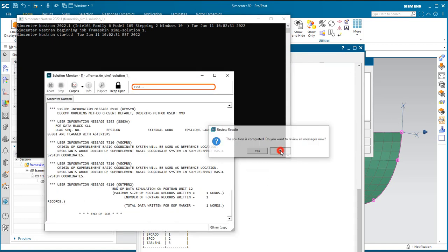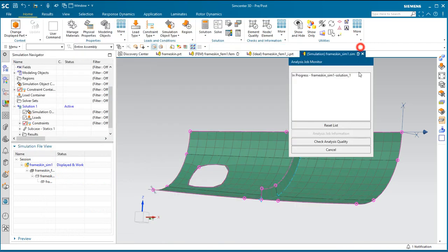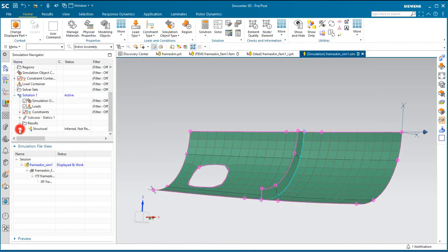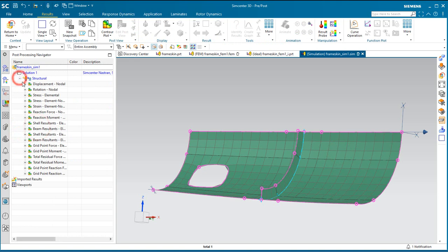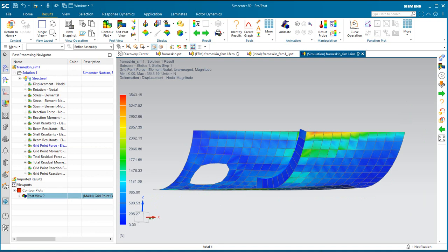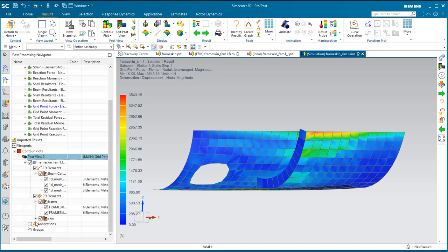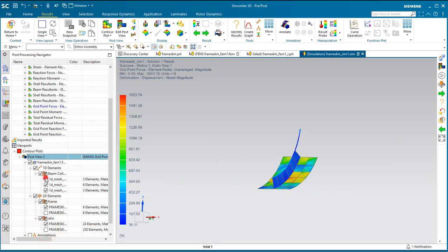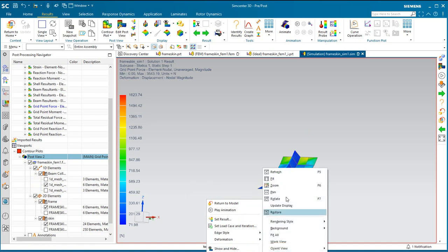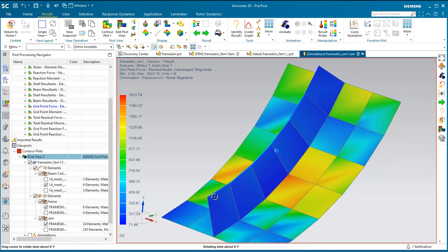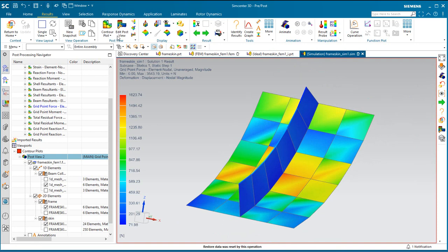And here I haven't paused the movie. It really only takes a second to run there. And the results that we're interested in are grid point forces. And the results that we want are the grid point forces just around the perimeter of the area of the model that we're going to break out. So here I'll turn off the meshes that are in the larger model and just leave on those elements that are in the breakout region.